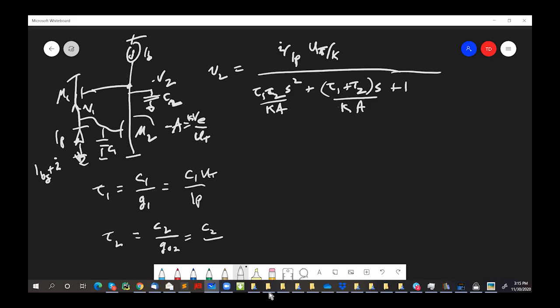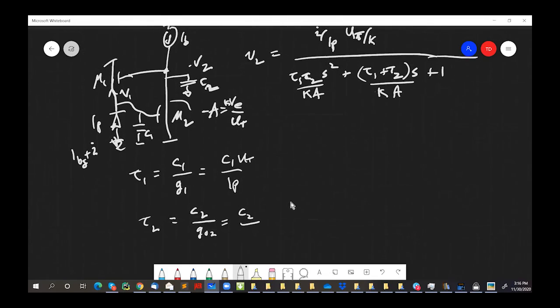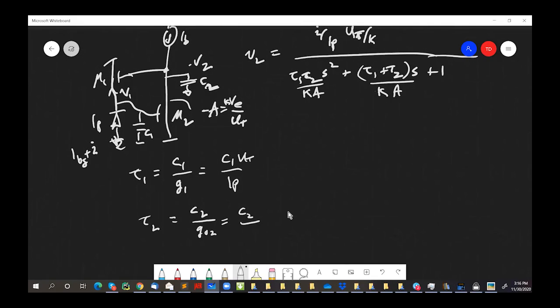Approximately, of M2. What was that again? The output conductance looking into M2. That's what we care about. Remember, it's an early effect, right? Not a transconductance, it's an output conductance. So basically, the output conductance of M2 is the bias current divided by the early voltage of transistor 2.